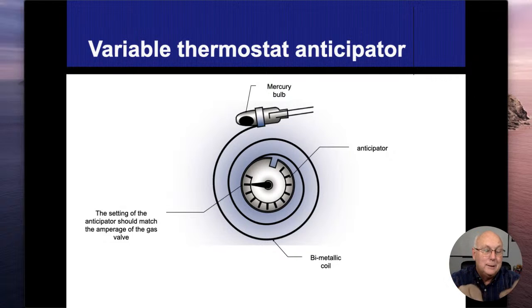into the house. This anticipator anticipates how that's working, and it says, all right, we're going up 1 degree every 5 minutes, and we're going to shut the fire down, and we know that we'll have still 5 more minutes of heat. And of course, I'm making up numbers. But it anticipates and it shuts the fire off early before it reaches the desired temperature, knowing that there's going to be enough heat in the heat exchanger to reach that, and that's all programmed with everything together.